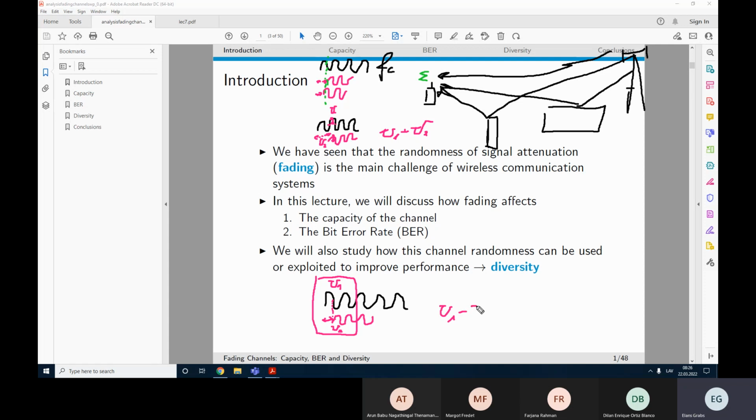So in fact, we are going to receive a smaller value of the amplitude for this signal because of this reflection. And the thing is that this process for fading channels is random. We already discussed that this time delay is a random process, and because of that, the amplification of our channel is also random. So we can say that, for example, this is our normal level of the signal, which we should get